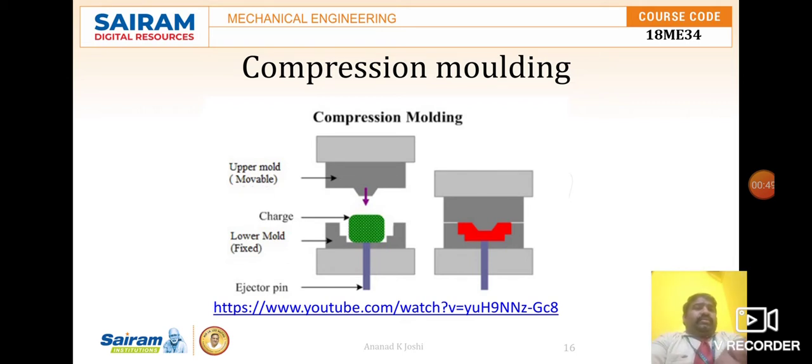So here, the additives are placed in the lower half of the heated mold, and immediately the upper half of the mold moves downwards. The direction is shown here: the upper half moves in a downward direction. A press compresses this heated material and forces it to fill the mold cavity. A hydraulic ram is often utilized to produce sufficient force during this molding process.